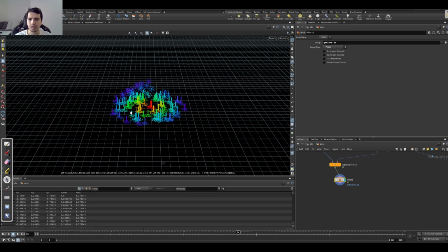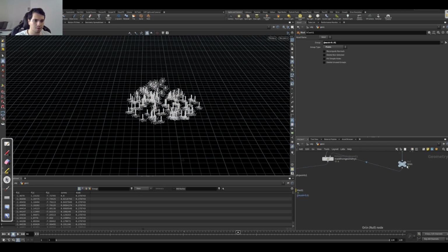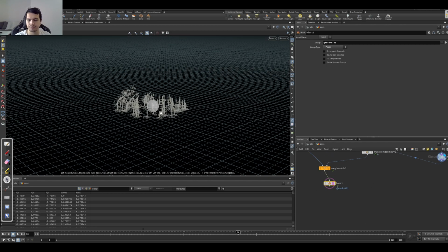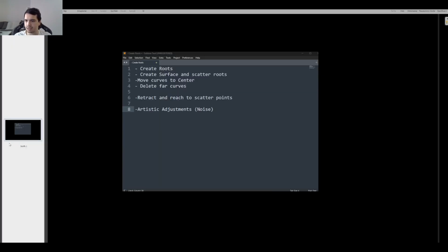Okay, now I want to work with these points. That's good. And I have my origin here as well. Let's just do the opposite template here. Yes. Now I want to connect these points to here. How can I use that? I will use a linear interpolation with curve U attribute. What will this do? You see the up top points will connect, but as it goes down, it will try to connect, not connect.